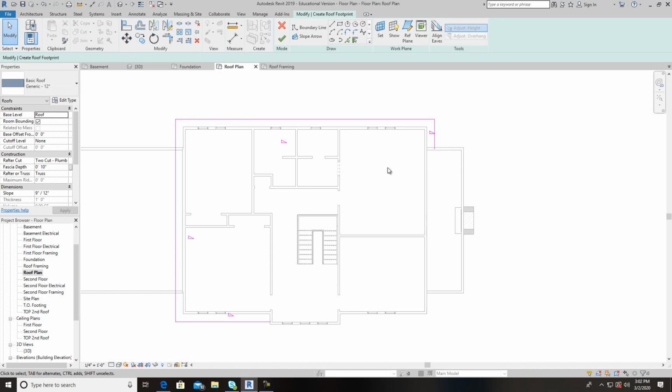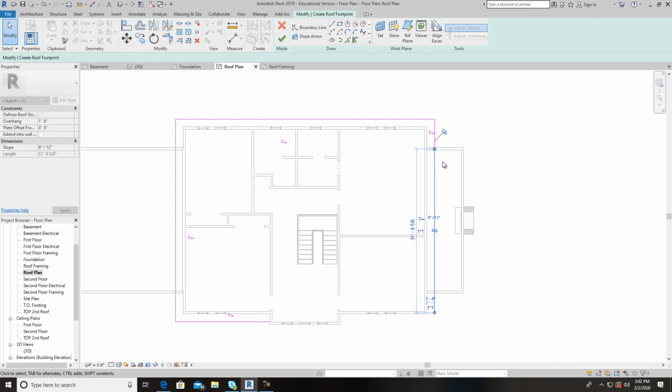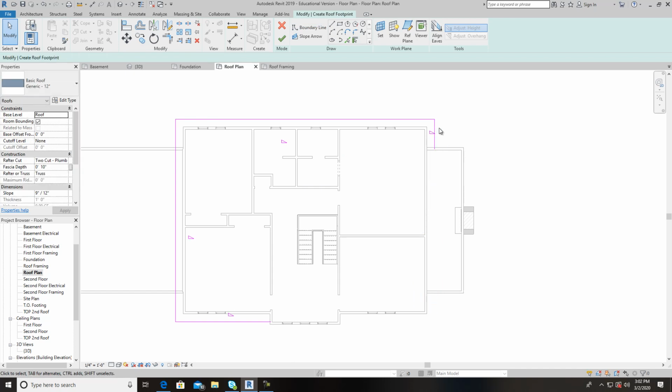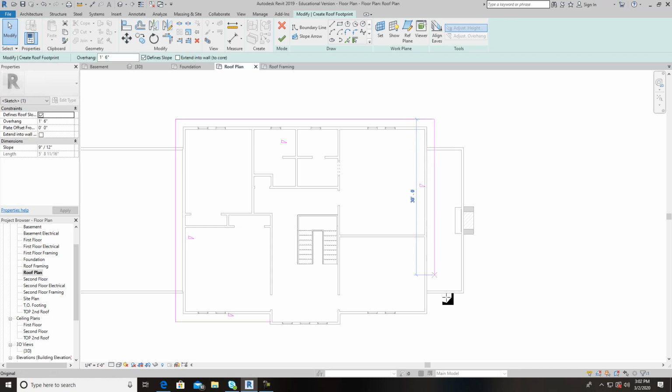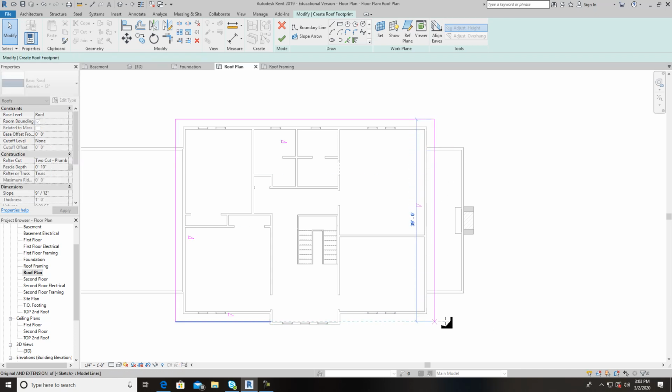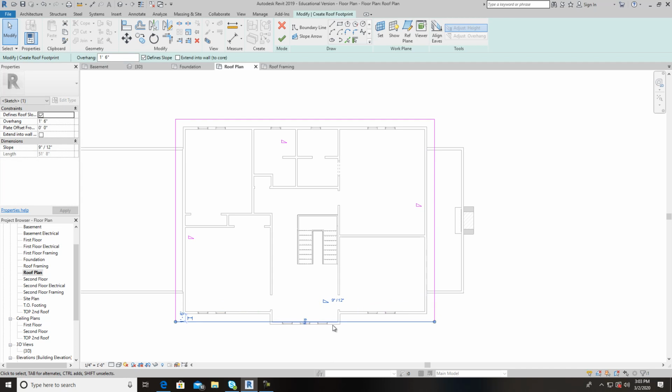Like if I had a line down here, let's say pick wall, and I come down there and do that. You can't grab it and connect it like that, because it's saying there's two walls or two roofs. You have to do it by one piece and bring it across, just like I'm doing. And this line here, we're not taking it all the way to the edge. You'll see that a little bit later. There's actually a dormer on that, and I'll show you how to do that in just a few minutes.